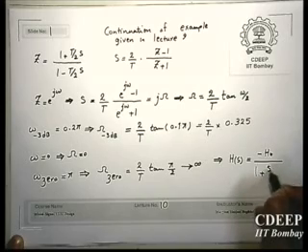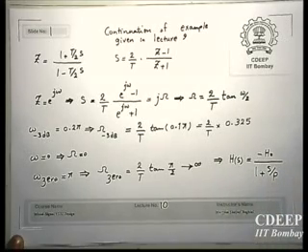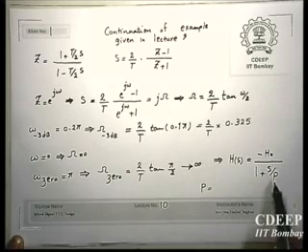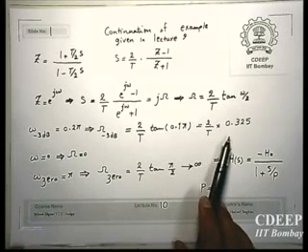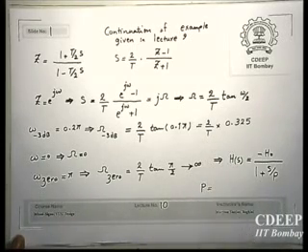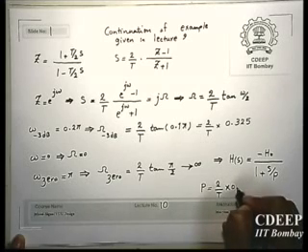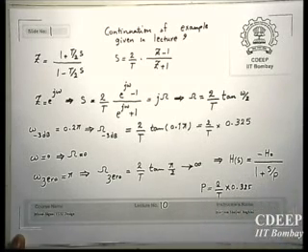So it will be something like this, H0 upon s plus P. And because this is first order, minus 3 dB will be same as the pole. Therefore, P easily will be, in continuous time, 2 by T multiplied by 0.325. And H0 of course is the gain at low frequency. So now you will get the counterpart of this filter in the continuous time domain.